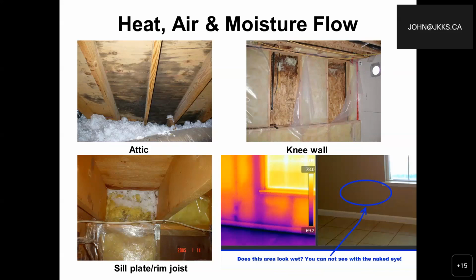We can see not only is there a temperature difference, on that little temperature scale bar off on the left-hand side, we see there's a difference in temperature occurring at the wood framing. Also, if we take a look at the dark blue spots, we start to see probably not just what we would call cold air gaps, but also the transmission of potentially water accumulation and moisture within this wall system.